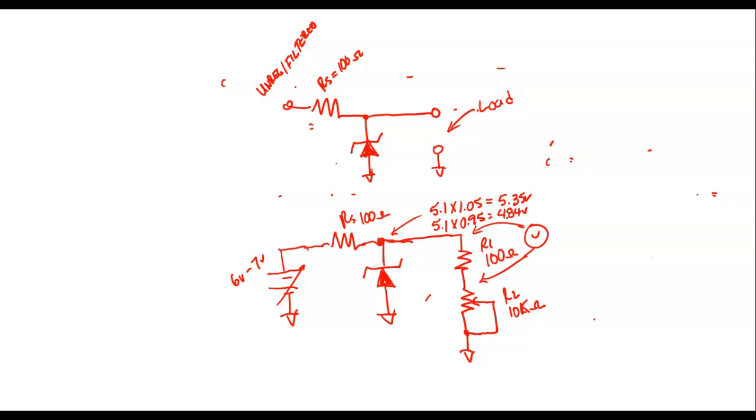When they designed the power supplies on this trainer, that's one thing they did. They designed these around 1 amp, so that's the maximum current. We don't know the minimum current, but they're 1 amp. Well, I do know the minimum current. Minimum current here would be 0, because I can disconnect the load. So right now, this 5 volt supply is requiring 0 amps.